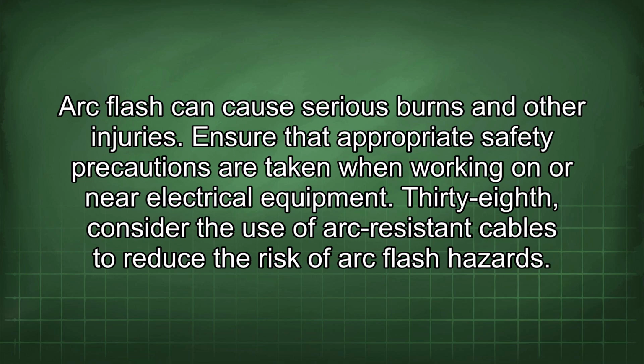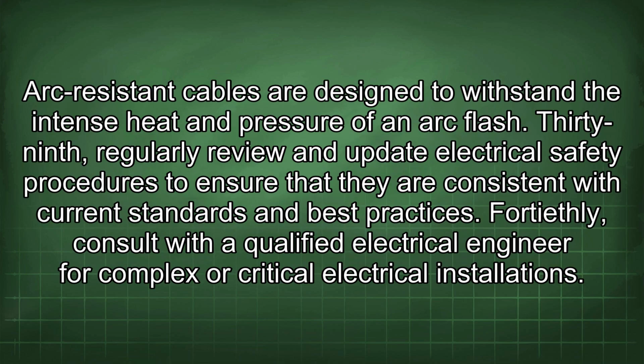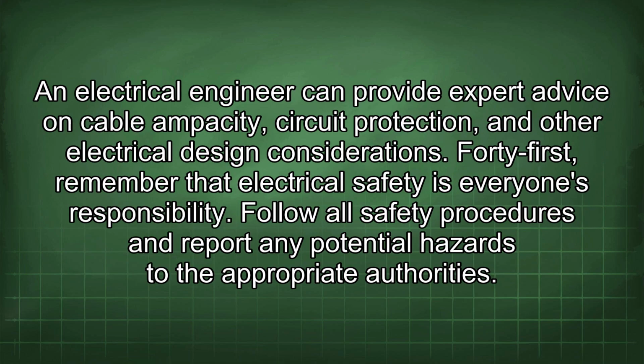38th, consider the use of arc-resistant cables to reduce the risk of arc flash hazards. Arc-resistant cables are designed to withstand the intense heat and pressure of an arc flash. 39th, regularly review and update electrical safety procedures to ensure that they are consistent with current standards and best practices. 40th, consult with a qualified electrical engineer for complex or critical electrical installations. An electrical engineer can provide expert advice on cable ampacity, circuit protection, and other electrical design considerations.